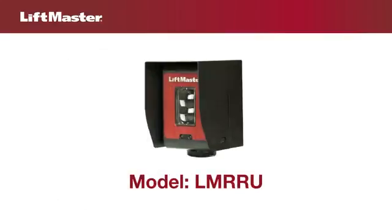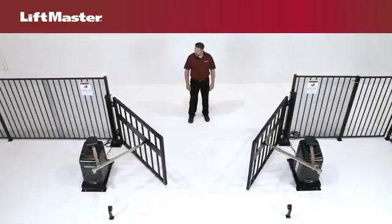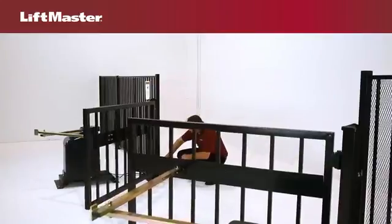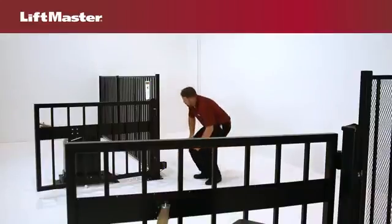Let's choose a LiftMaster monitored photoelectric sensor for the closed entrapment zone. Photoelectric sensors are considered non-contact sensors. If the beam is blocked while the gate is moving, the gate will stop and reverse. The obstruction will have to be removed before the gate will travel in the closed direction.